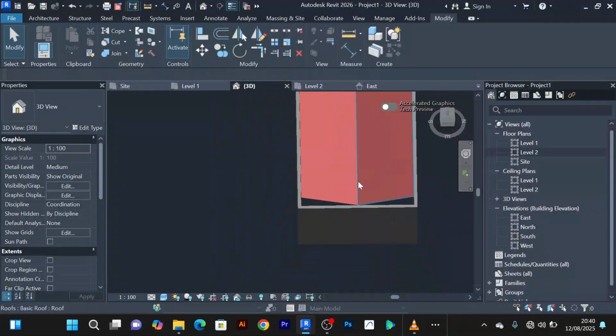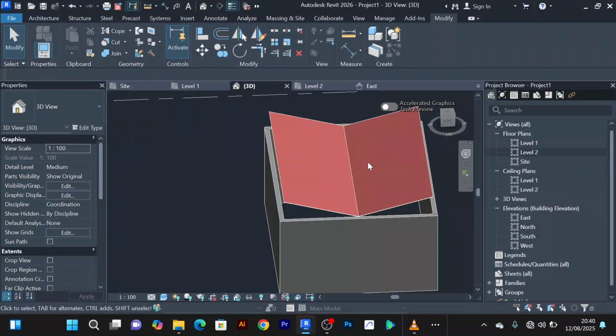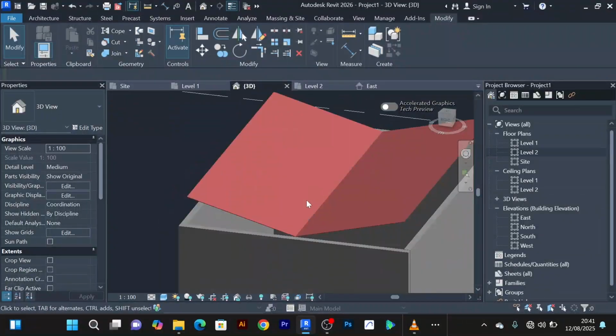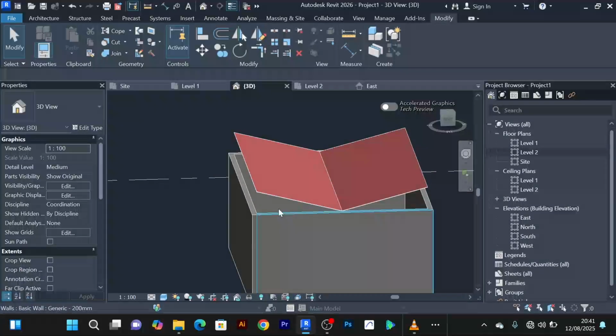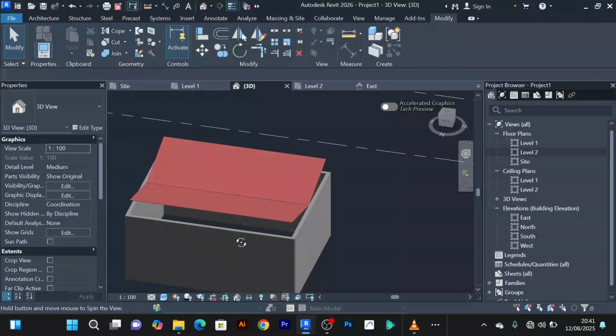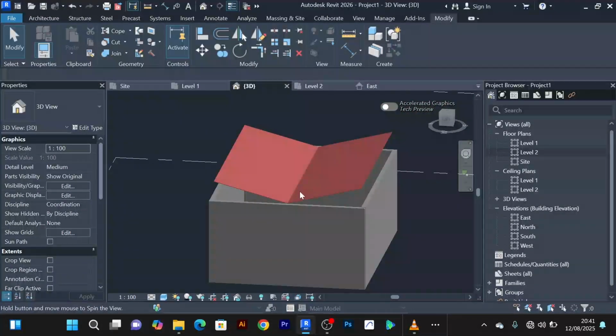The roof is supposed to pour water in the middle. All the water is collected from the middle, and of course now with this one you need to be very careful because the water point is in the middle of the house. That means this part here needs to be properly constructed, otherwise your house will leak. Now of course with this type of roof you also use parapet walls to cover up these sides, so that they are properly hidden. So this is how you can create your butterfly roof.